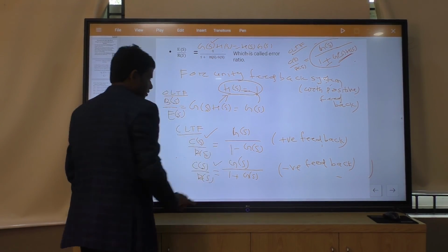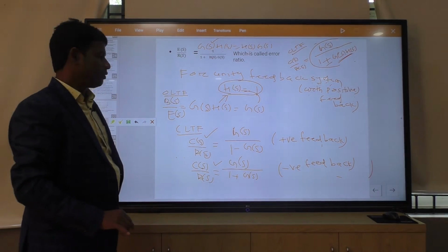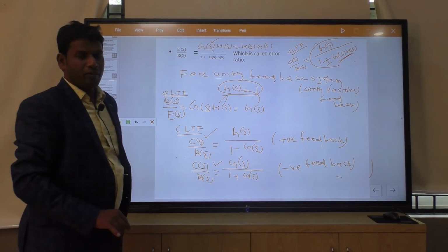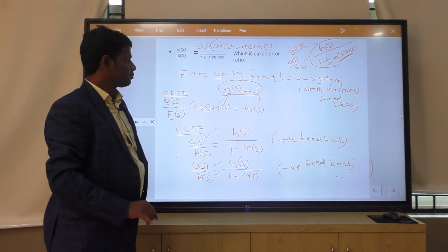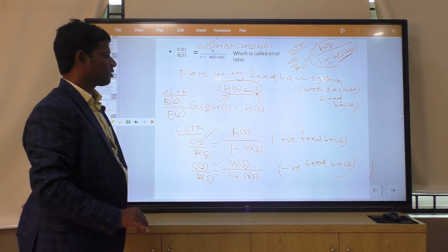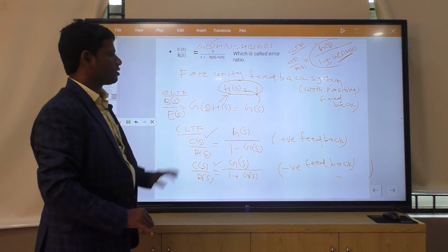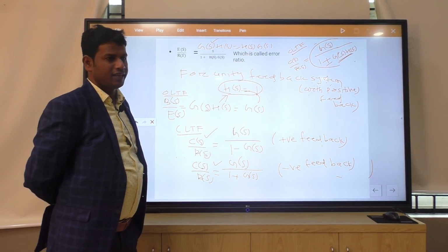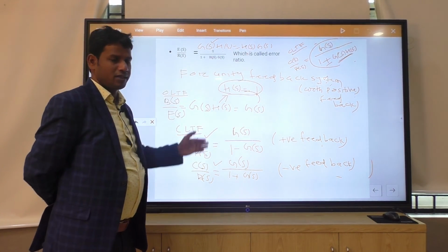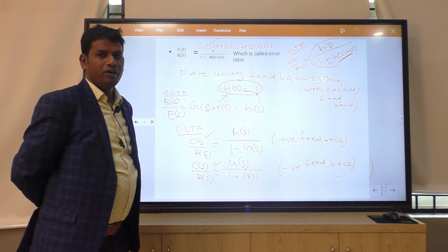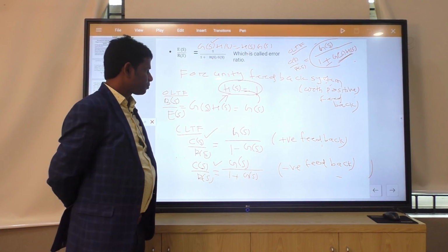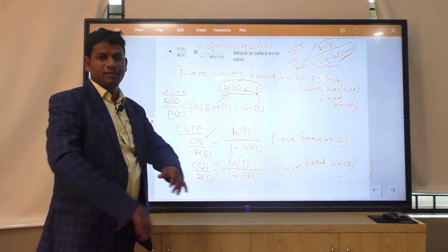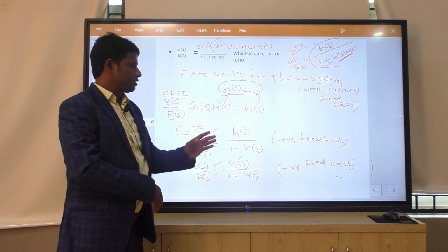The second one is the negative feedback system with unity feedback. So this was the discussion about the canonical form of a closed loop control system, which is very important for control systems because these are all feedback control systems. A closed loop system is also called a feedback control system. These are the representations of the different blocks and their equations, and how you determine the open loop transfer function and the closed loop transfer function. So we discussed these parts in today's class.